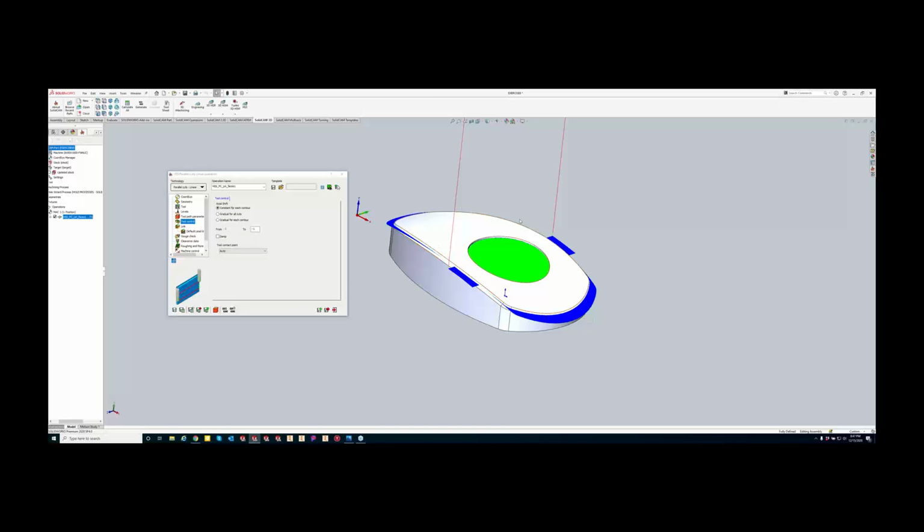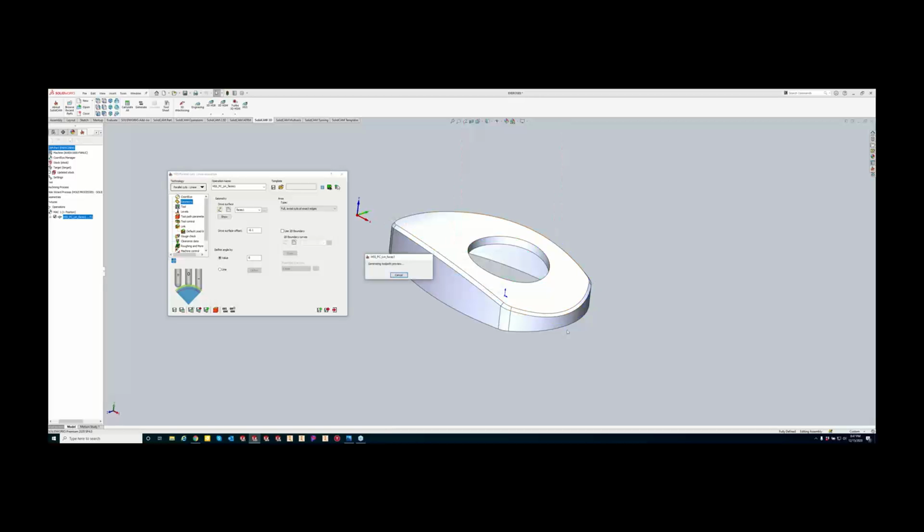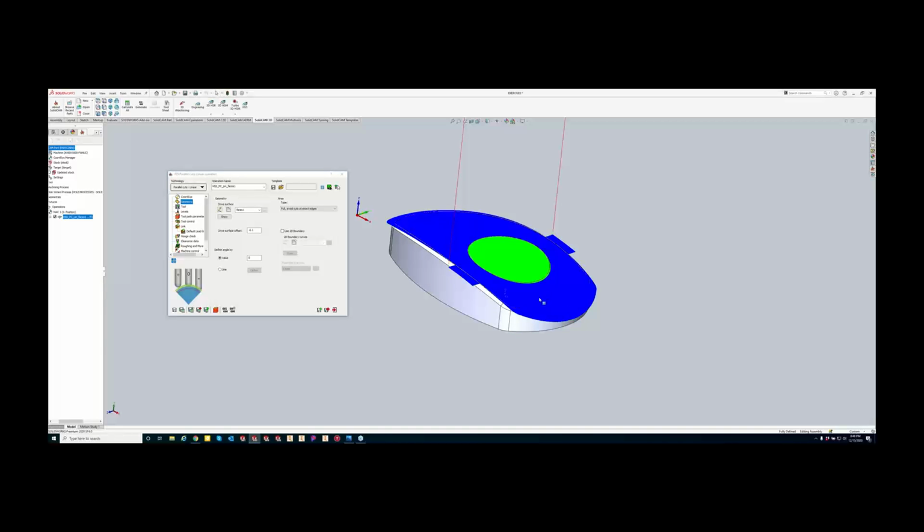It'd be more for doing that chamfer around the outside, and we'll actually do that in one of the next classes coming up. But if you guys are looking to shift down your tool path in the part, definitely come to your geometry and do a drive surface offset of, we can do 0.1 millimeter. It should look identical. And there we go.